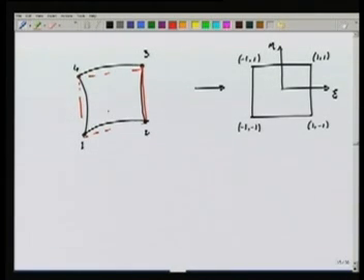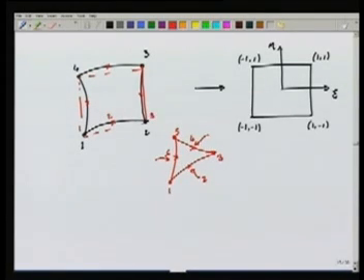So what do we do? We say, okay, fine, let us put another node somewhere in the middle. We could do a serendipity mapping. Or if I have a triangular element, I will take these middle nodes; that is, I need to know these points in the middle of these curved edges. I need to know their coordinates. So this will become my point 1, this will become my point 2, this is becoming point 3, 4, 5 and 6. Similarly, this will be 1, 2, 3, 4, 5, 6, 7, 8.